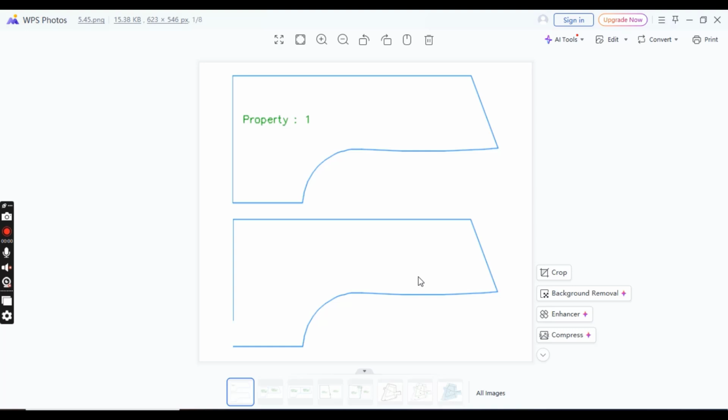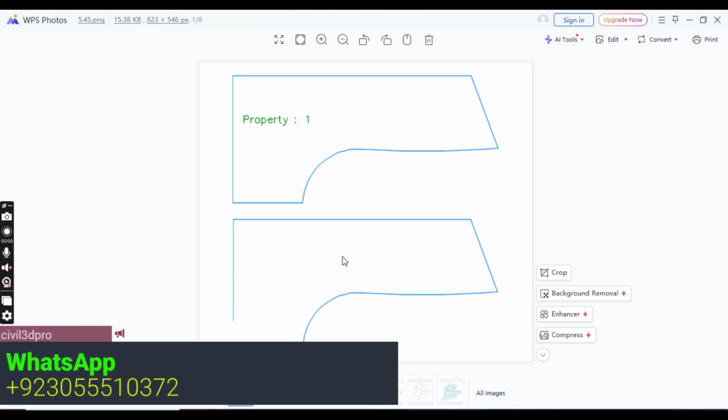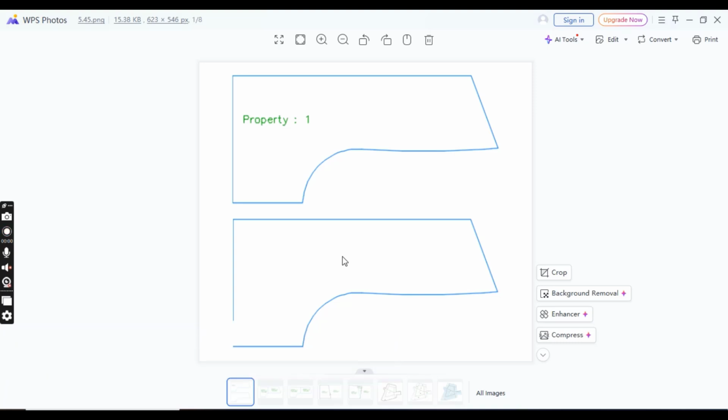You also saw that even though a parcel can't be erased, if you erase the appropriate parcel segment, the area contained within a parcel is assimilated into neighboring parcels. So remember that you can delete parcels if you move them to a new site and delete that site. This is an easy way to delete parcels that are not needed in the drawing.